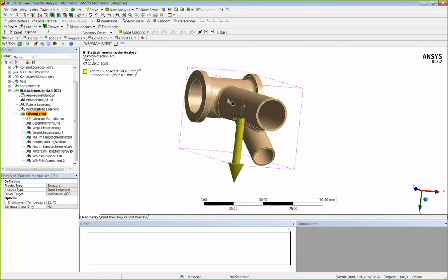For structures like these, the guideline says we could take the volume, which would be 40,000 cubic millimeters here, multiply that by 4, which would be 160,000, and compare that to the surface, which would be 31,000. So I would have 160,000 divided by 31,000, which is around 6. And then I have an estimate of what this characteristic length could be.